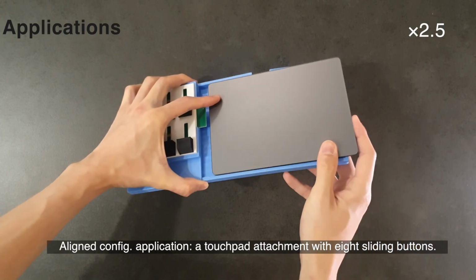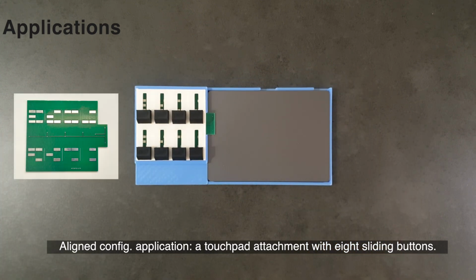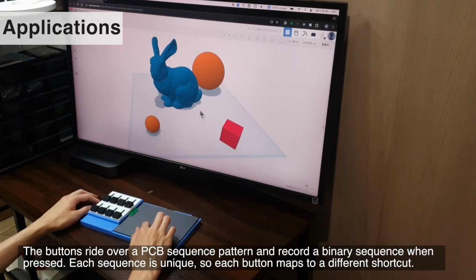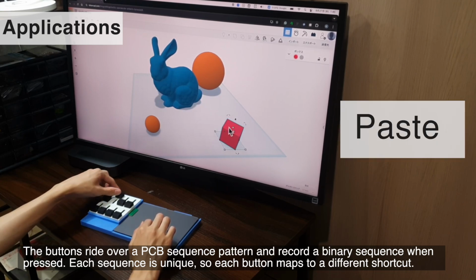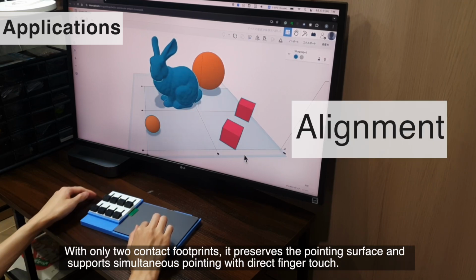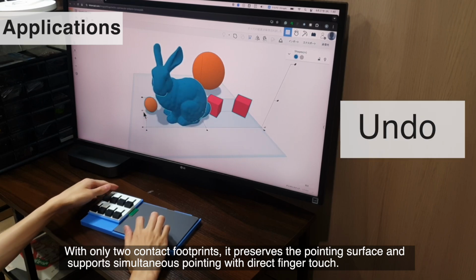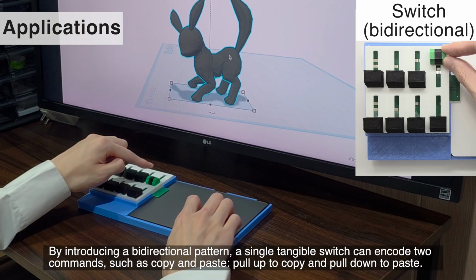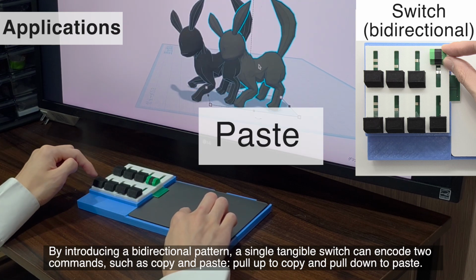Aligned configuration application, a touchpad attachment with 8 sliding buttons. The buttons ride over a PCB sequence pattern and record a binary sequence when pressed. Each sequence is unique, so each button maps to a different shortcut. With only 2 contact footprints, it preserves the pointing surface and supports simultaneous pointing with direct finger touch. By introducing a bidirectional pattern, a single switch can encode 2 commands, such as pull up to copy and pull down to paste.